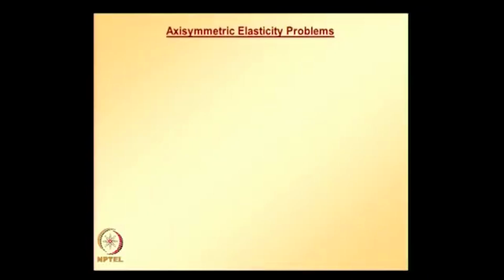We are looking at axisymmetric elasticity problems. In the last class we looked at the axisymmetric linear triangular element. Basically, 3-dimensional elasticity problems involving axisymmetric geometry and loading can be treated as 2-dimensional problems, and in the last class we looked at the governing differential equations, and also at how to derive finite element equations for a linear triangular element. We will continue with that, and before we do that let us look back at what we did in the last class.